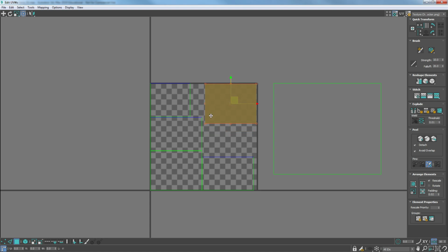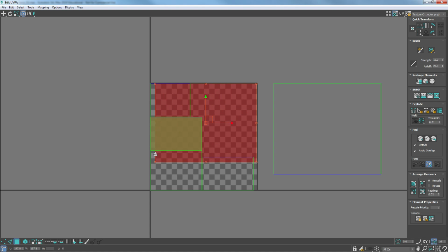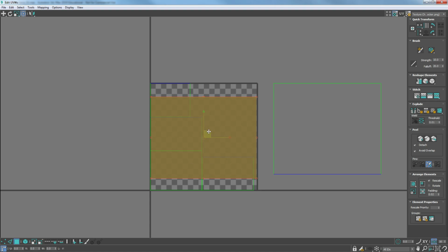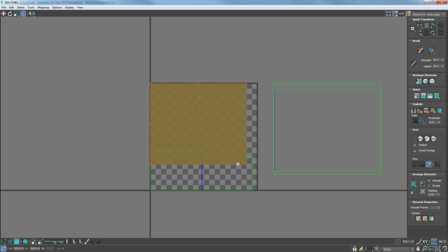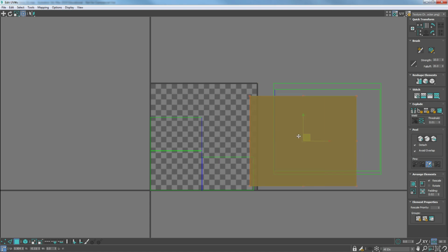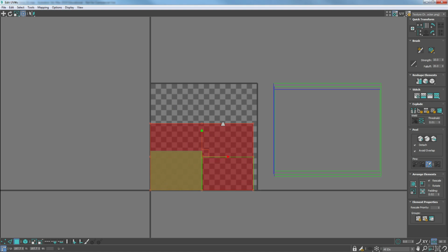You hold shift before you put the... I'm holding control right now because it'll maintain the actual proportion. So when I scale, it'll scale in proportion. If I hold shift, it'll stay on an axis. And if I hold control, it keeps the proportions. And that's important because when I did the flattened mapping originally to get the mapping set up, that's where the proportions got established, and I want to make sure that they keep from the 3D space to the texture space.